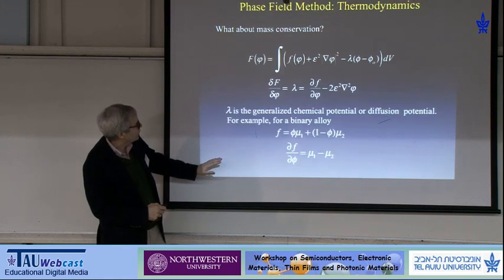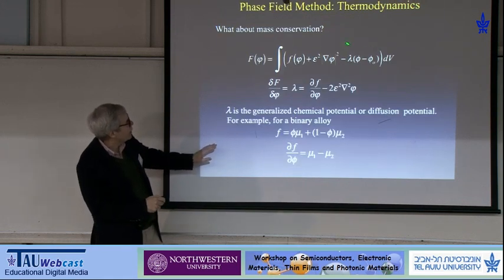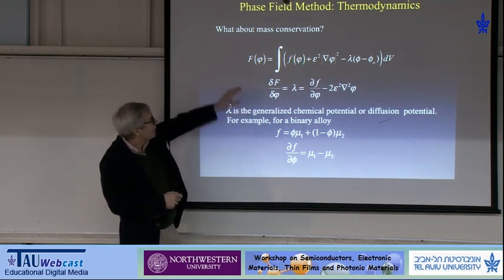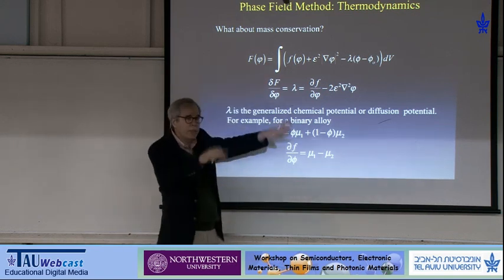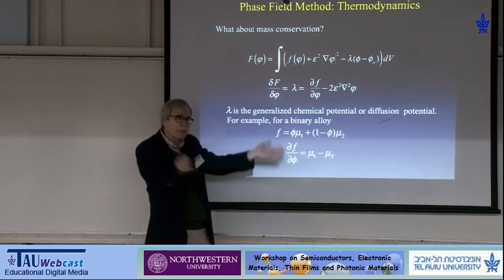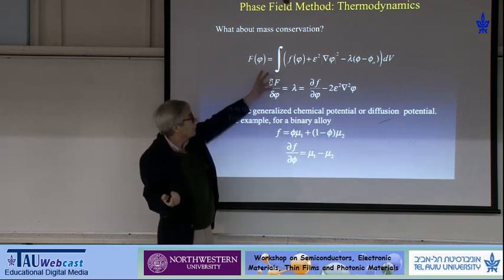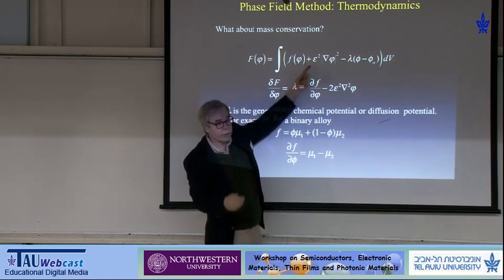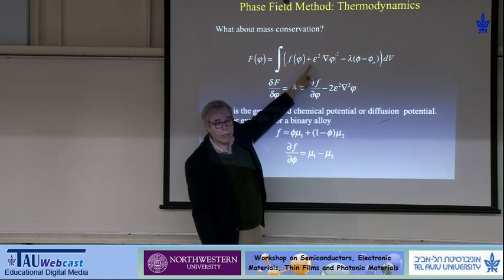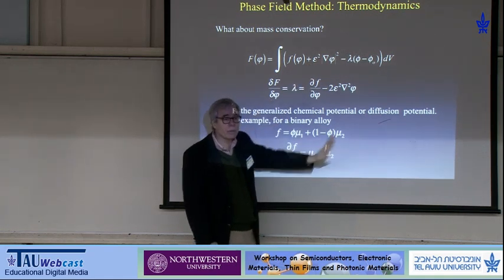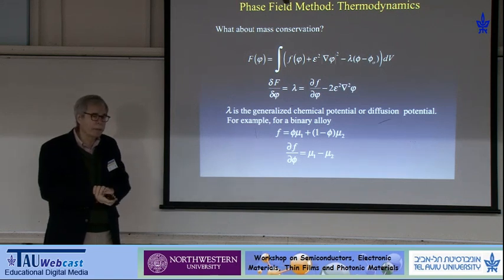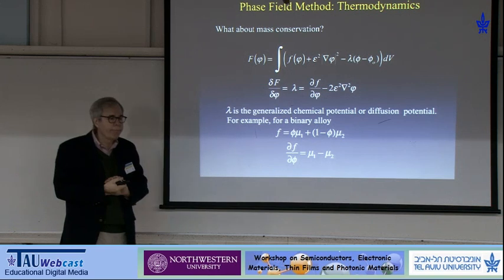There's a very strong connection between this, let me go back to the free energy, and the evolution equations. What that means is that all of these equations decrease the energy of the system. And so you have this general energy framework that allows you to write things. If you were doing magnetics, you could add magnetic energy. If you were doing electrostatics, you can add electrostatic energy. If you're doing elasticity, you just add more energy functions here. So it's very easy to generalize this, but that's the reason why it's so hard. It's just nonlinear. And in the solidification case, they're two coupled nonlinear PDEs, and so you just can't do much analytically with it.